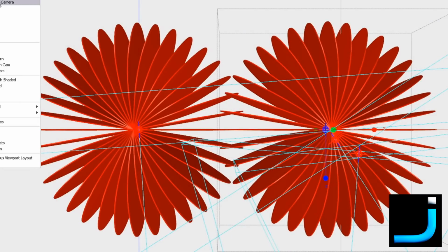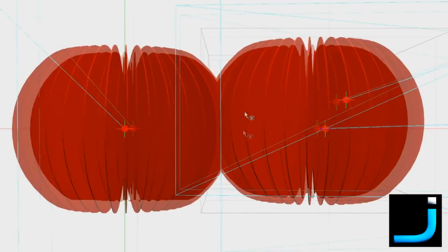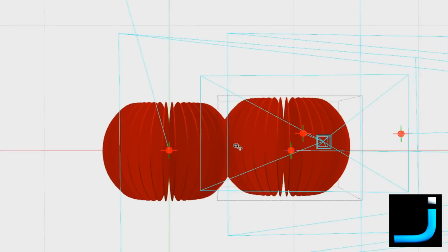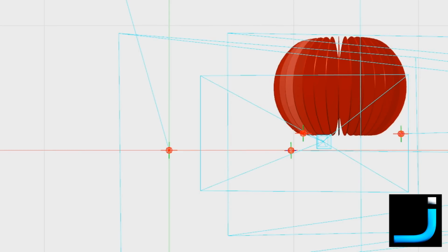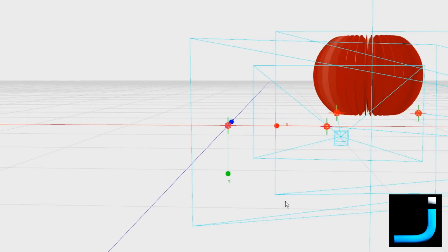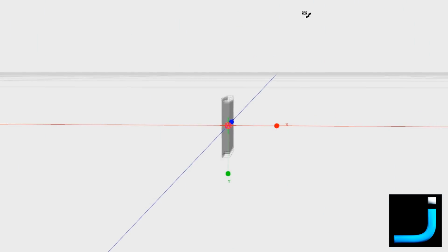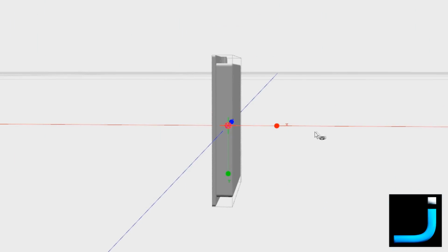Now, it's not the end of the world, because there are things that we can do. And this is the idea of diversity antennas, for example. So here's our plane. We'll leave the radiation pattern on that for clarity. We'll turn off our rubber ducky antenna, and let's have a look at a typical diversity antenna. Now, we're all familiar with the panel-based antennas.